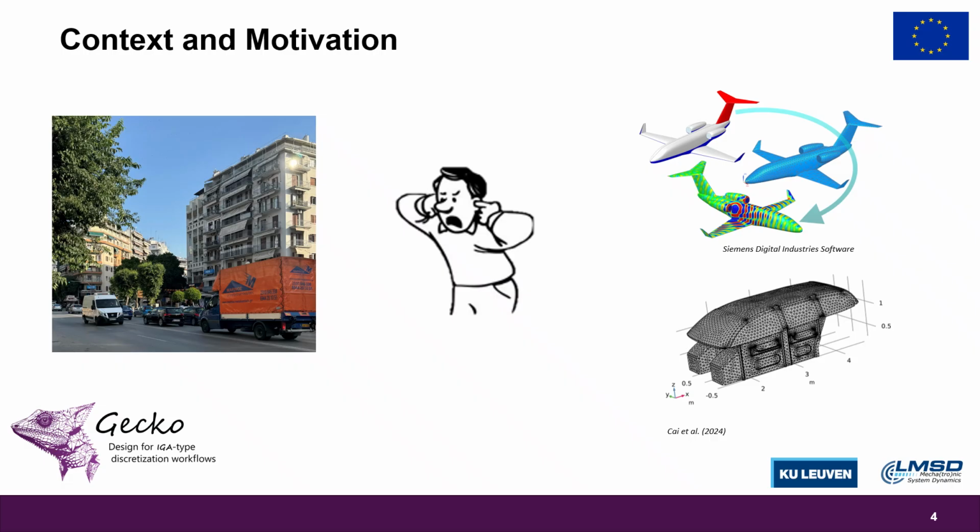The reason why I use the boundary element method is that you only need to mesh the boundary, and CAD geometry is usually represented as a boundary representation, meaning that they fit very well with BEM. Furthermore, the BEM also inherently satisfies the Sommerfeld radiation condition, which makes it quite attractive for radiation problems.